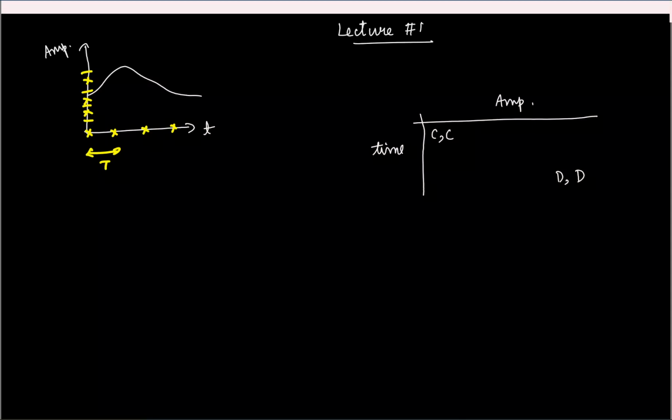And of course, to convert from analog to digital, you can do it in two ways. You can either first discretize the time and get a discrete time continuous amplitude signal. And what is this process of discretizing the time axis called? Sampling. I'm sure everyone is aware of that. And once you discretize the time axis, you can go ahead and discretize the amplitude axis. And what is this called? I'm sure you would have heard this term in some form or the other.